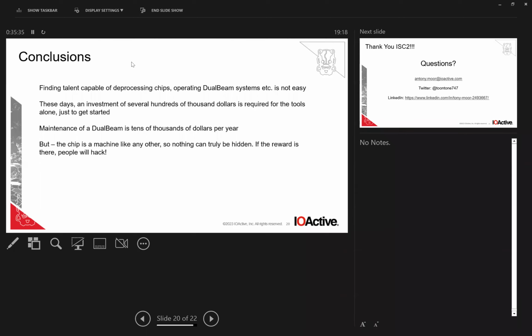Almost all secure devices will have an active shield. So it's still possible to bypass that: you make a hole, you cut a couple of tracks to give you access to where you want. But as long as you remake those tracks, the chip is not sensitive enough to sense there's been a breach. So you can't do a huge reroute of a track because the signal is timed. But if you make them roughly similar, it's not straightforward here.